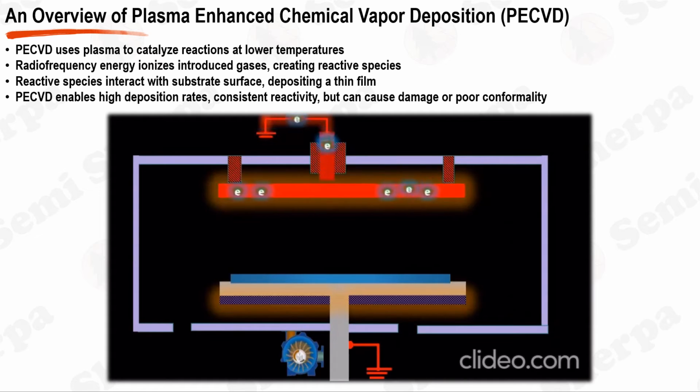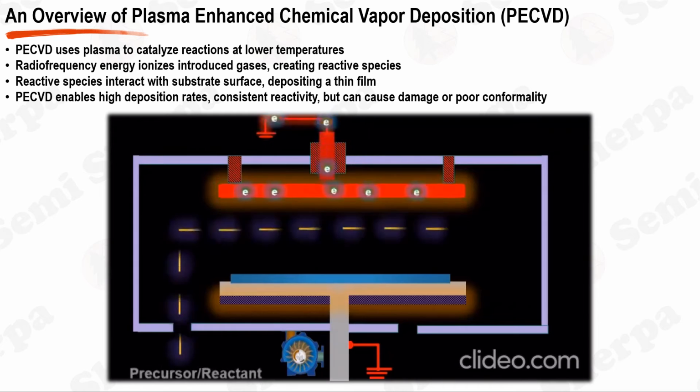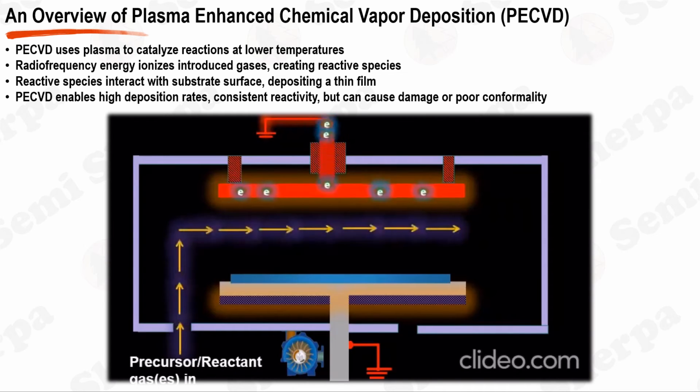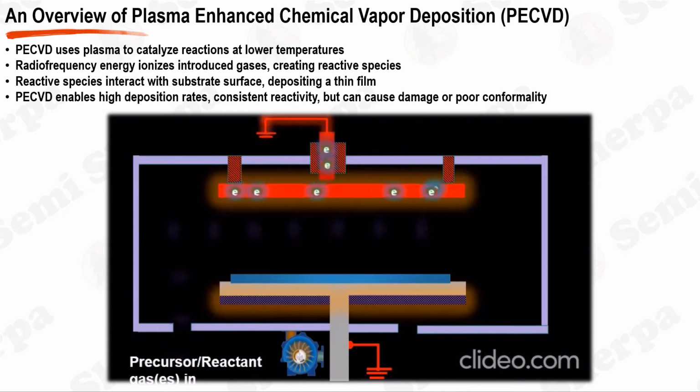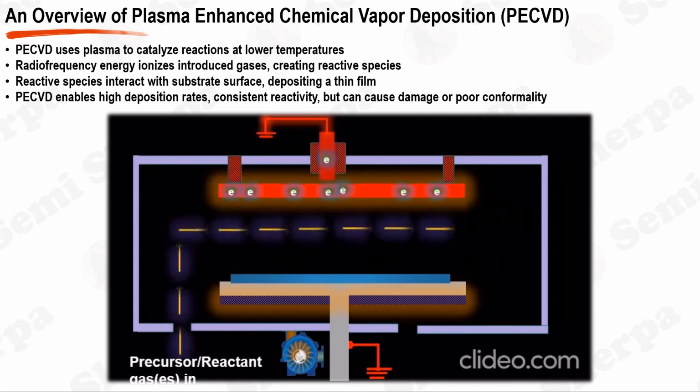Moreover, PECVD exhibits a unique characteristic when depositing multi-component films. The reaction rates of each component particle tend to be similar, resulting in a relatively consistent reactivity across the different material components. This results in films with good mechanical strength and moisture-blocking properties.